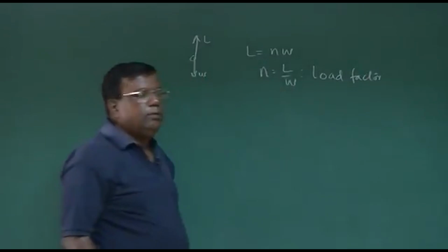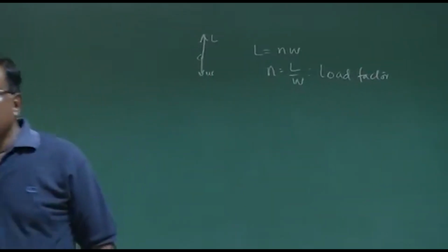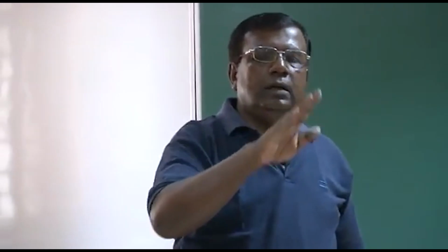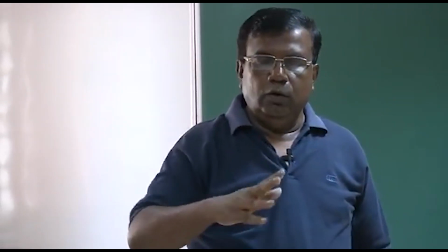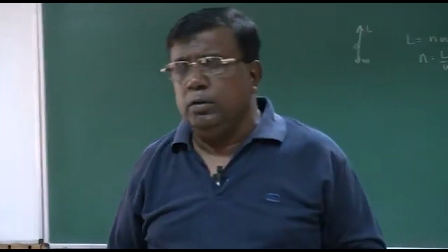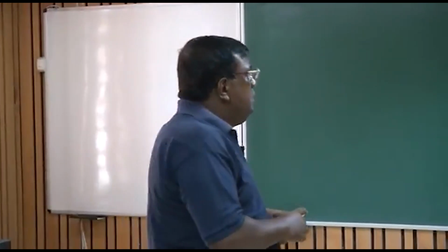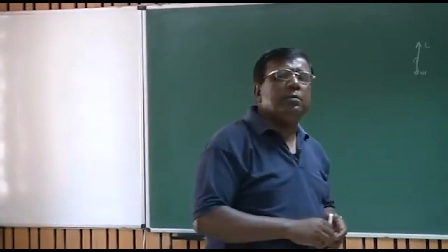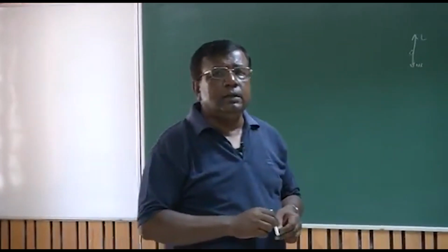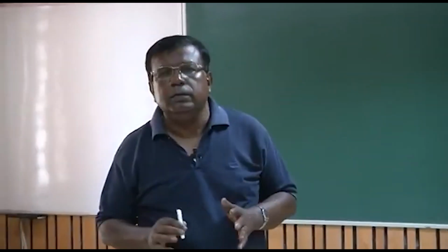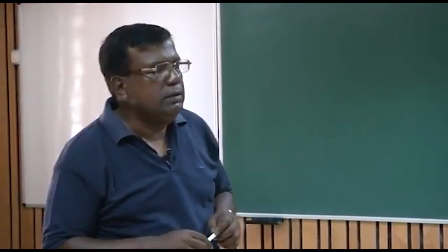Typically, you will find that fighter airplanes can do a straight pull-up like this. They can do a roll pull-out like this. For a straight pull-up, modern aircraft can now go up to a load factor of 8G. For a roll pull-out, it is between 4 to 6G, mostly 4 and 5, around that.